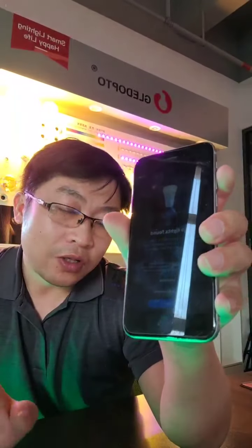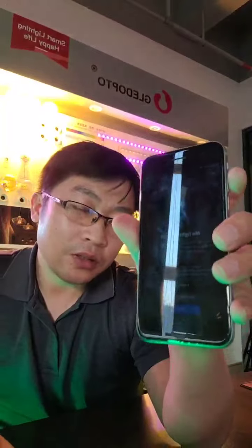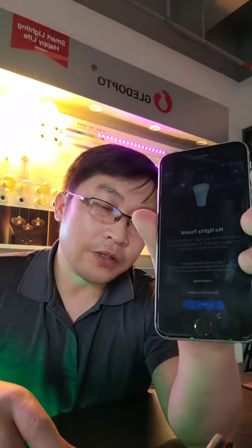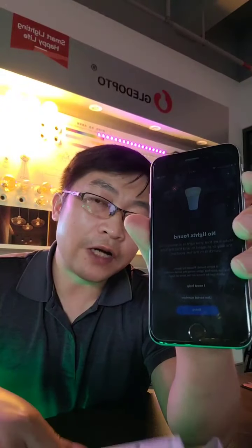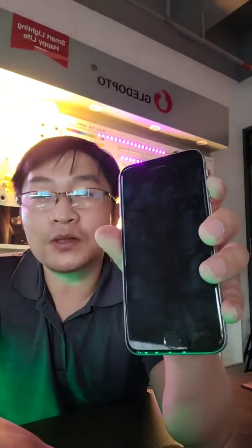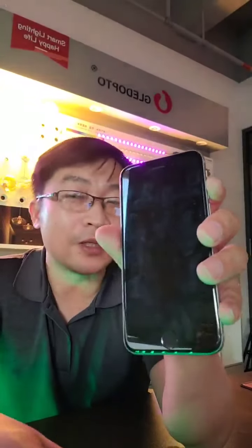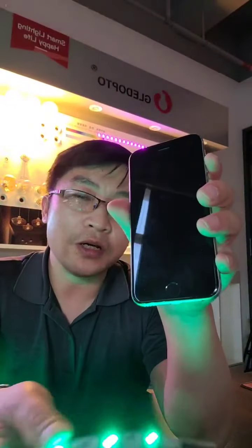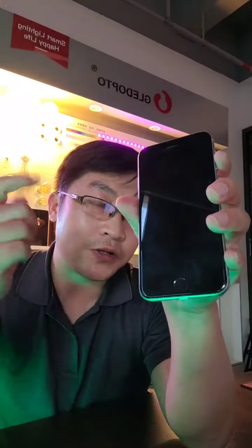Because this controller has already been found by our colleague doing the testing. So we need to make the controller back to factory resetting mode. Let's power on and off 5 times, not 4 times, 5 times directly, until you see all the LEDs are lighted on. It means the factory resetting is done successfully.